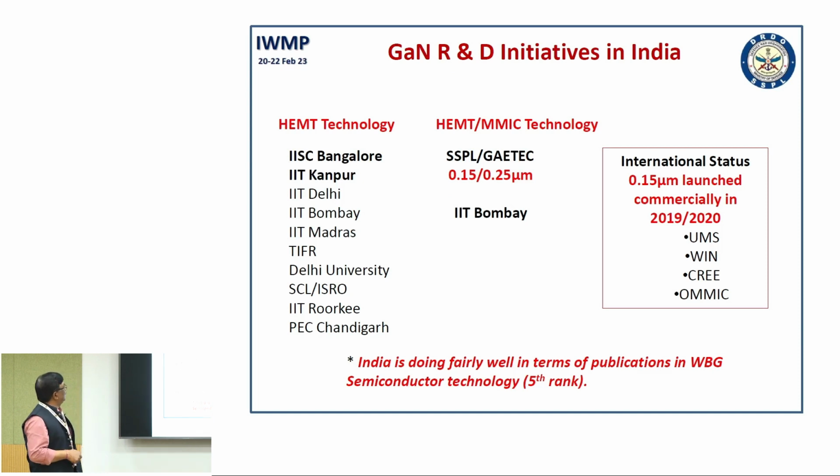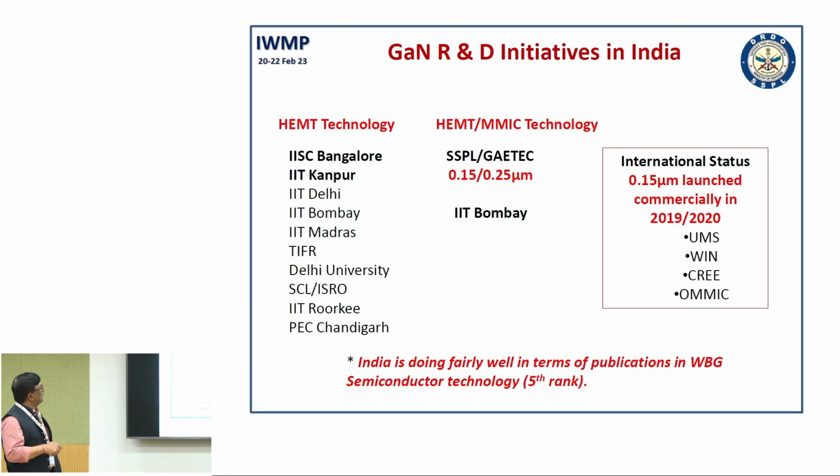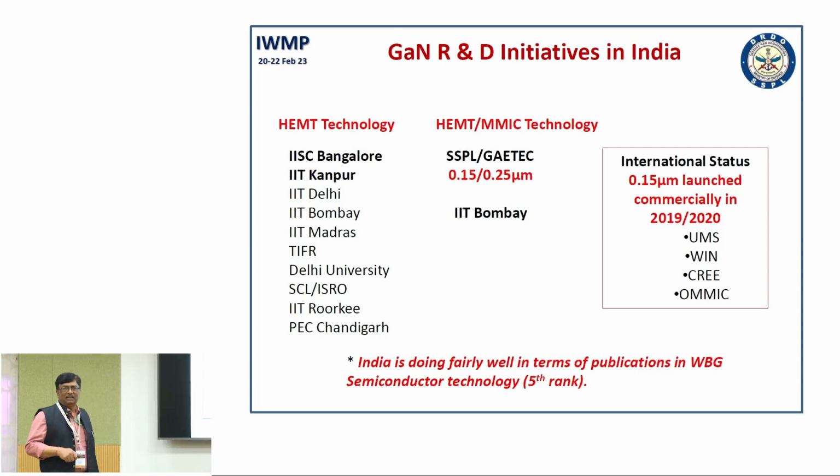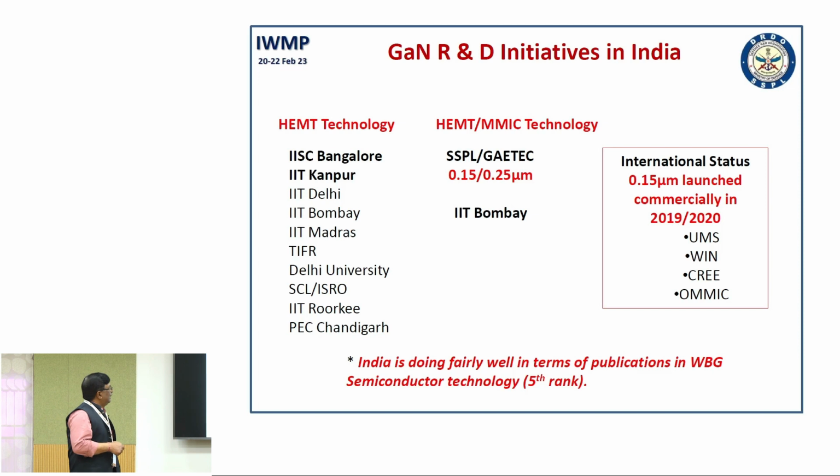To briefly look at the gallium nitride R&D initiative in India, a lot of places are working on this. HEMT technology is being explored at various institutes, and HEMT MMIC technology, to the best of my knowledge, only 2 places are presently working, that is IIT Mumbai and SSPL, for high frequency communication applications. And at my place I am working on 2 gate lengths, 0.15 and 0.25 micron, for X and Ku band application.